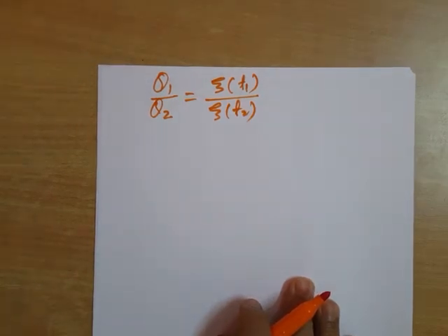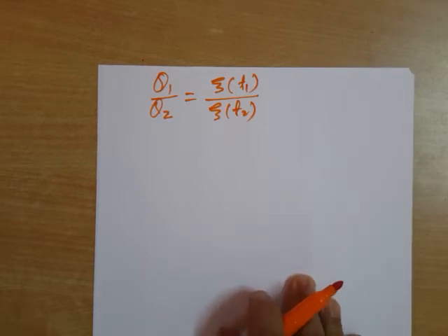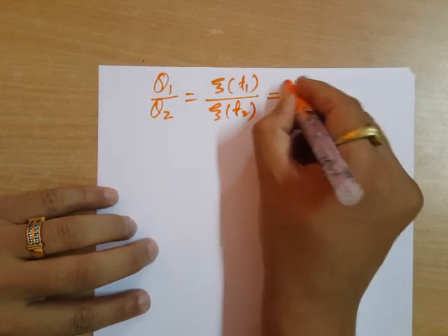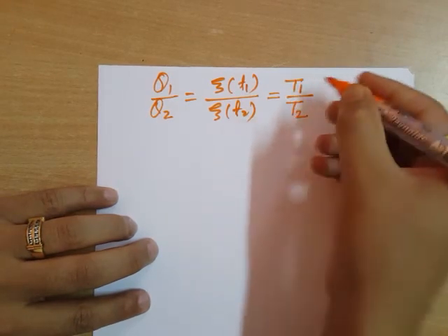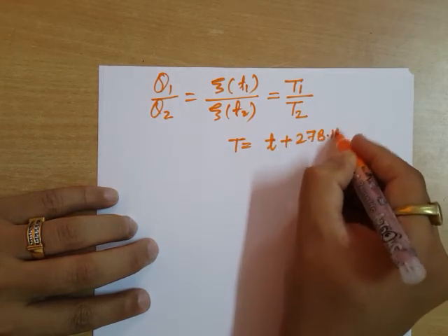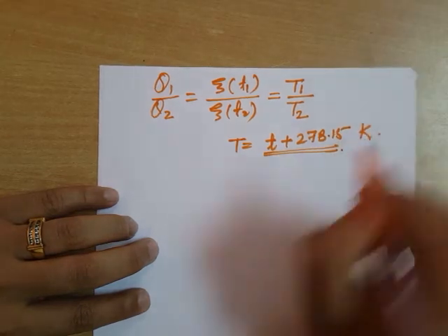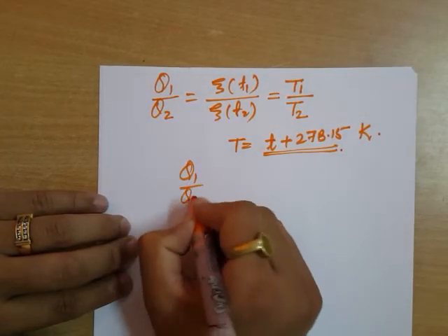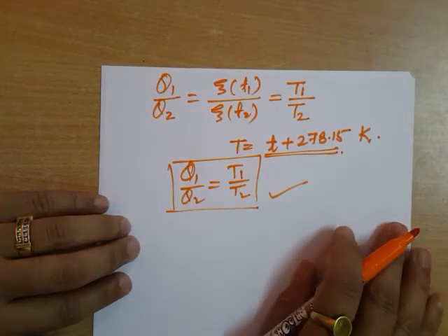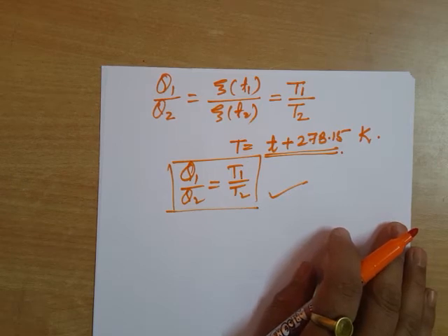Lord Kelvin said that this function we will consider as absolute thermodynamic temperature, and that's why we write this as T1 and T2. What is absolute thermodynamic temperature? It is the temperature in degrees Celsius plus 273.15, that is Kelvin. So Q1 by Q2 equal to T1 by T2 becomes a basis for temperature measurement even, and this becomes a representative of a reversible heat engine.